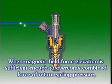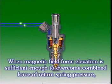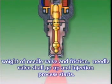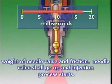When the magnetic field force is sufficient to overcome the combined force of the return spring pressure, the weight of the ball valve and friction, the ball valve shall go up and the injection process starts.